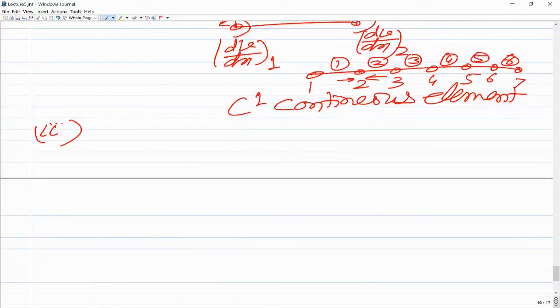So here in finite element, the unknown constants like a naught, a1, a2, a3 do not have physical meaning, so we express those unknown constants in terms of the unknown values of the displacements, and if required its derivative, at the node points. We don't satisfy any boundary condition over here, but we just express the unknown constants in terms of what we call the elemental degrees of freedom.